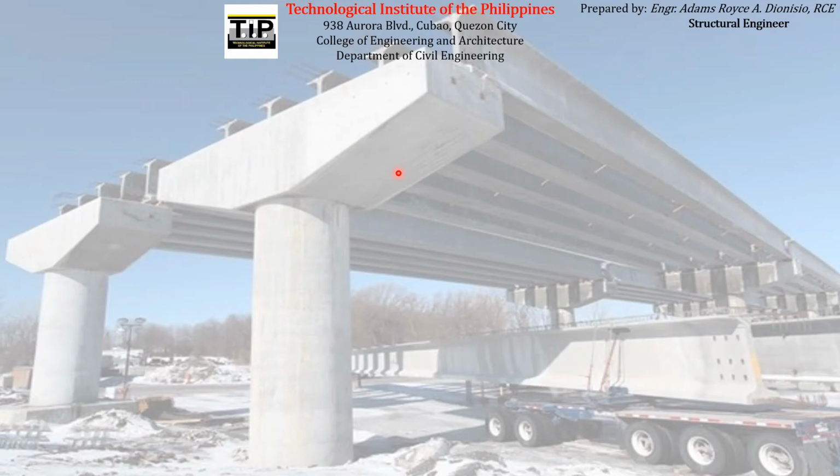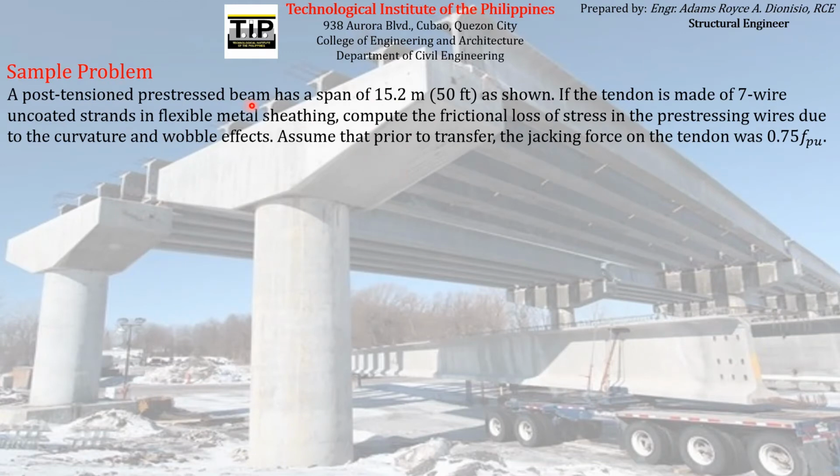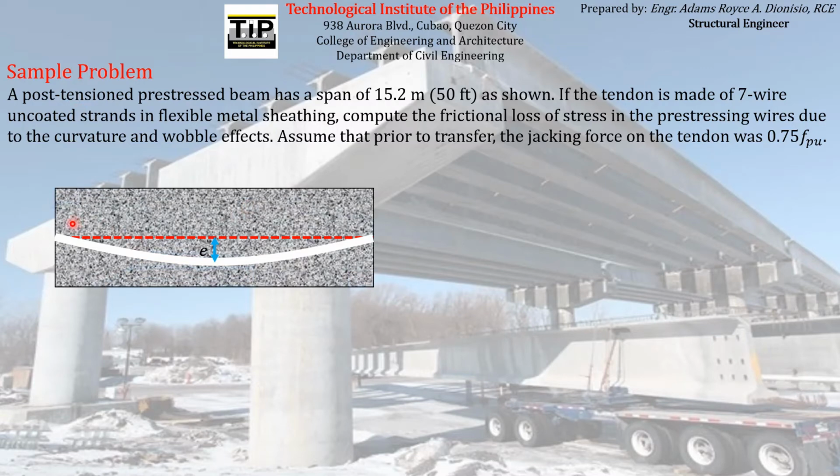So to better understand how to compute the pre-stress loss due to friction, let us apply it in a sample problem. A post-tension pre-stress beam has a span of 15.2 meters as shown. So this is the post-tension pre-stress beam. Obviously it has a duct placed first before the concrete is poured, and after the concrete already attained enough strength, the pre-stressing reinforcement will be inserted.